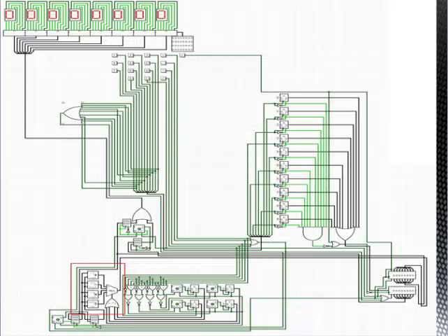This is where the arithmetic logic is implemented. Each module represents a complicated system of logic gates that can add, subtract, multiply, or divide a number up to 32 bits of space. It takes input from what is known as a register and outputs to another set of registers.